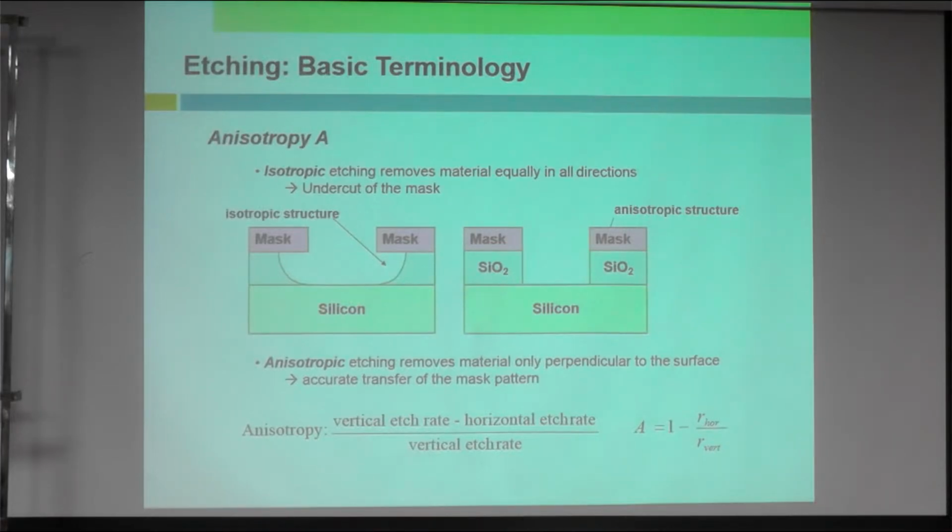So this can be a consideration during the design process. If you consider that the thickness is at a certain thickness, you want to remove the material, then the undercut happens, then you might be able to calculate it in advance. If you dip into the wet etching process for a few minutes, for example, then you will get undercut.